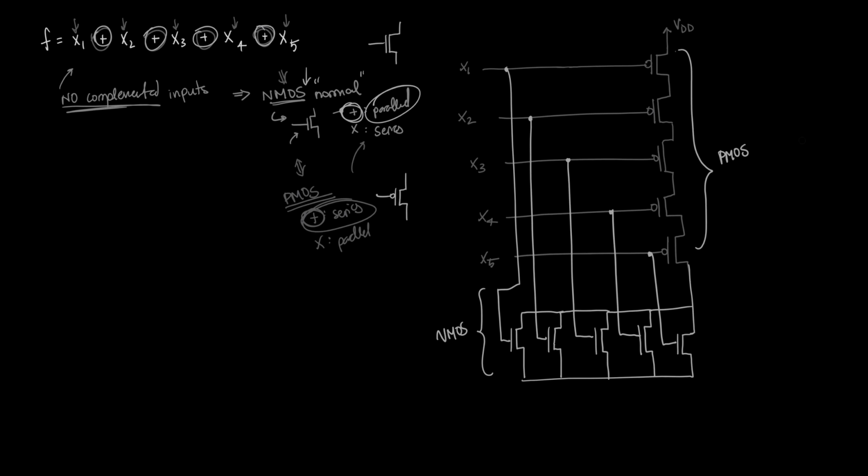So we can go ahead and connect this part to ground like this in the diagram. And then recall that NMOS and PMOS are always on opposite extreme ends of the diagram, and the final output is always going to come from right in between them. So our final output can come right from here. This is right between the NMOS part and the PMOS part.